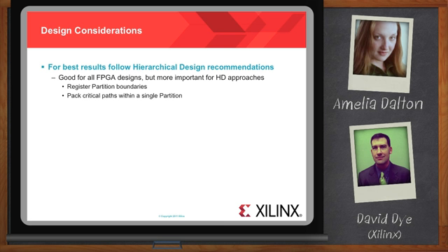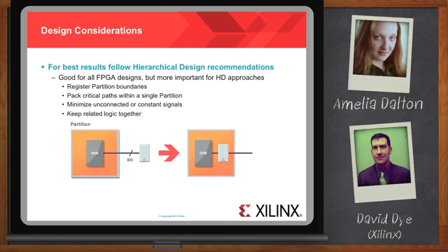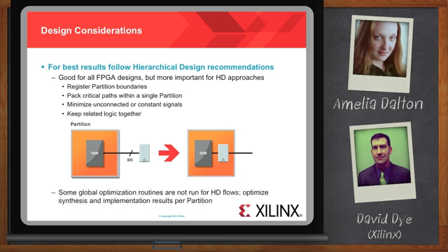Makes sense. A third suggestion is to keep the number of unconnected or constant-driven ports to a minimum. This may be unavoidable for some IP, but it reduces the chances that dead logic may remain in your design results. Okay. And then finally, any logic that is best packed together should be kept in the same partition. Right. In this example here, if a block RAM sources a register, implementation tools will want to pull these together into a single site. Now, keep them in the same partition to make sure that that can happen.